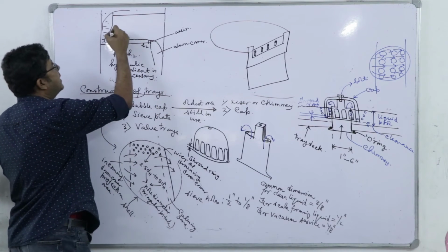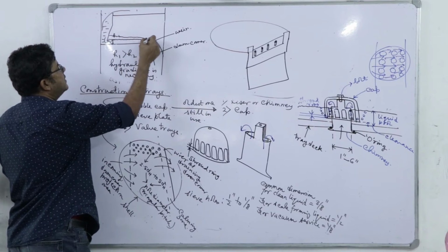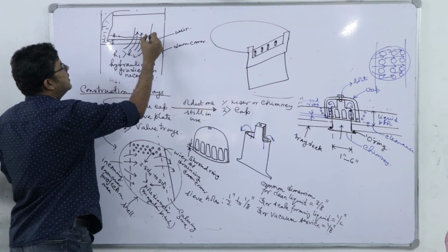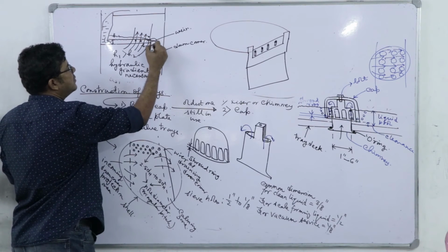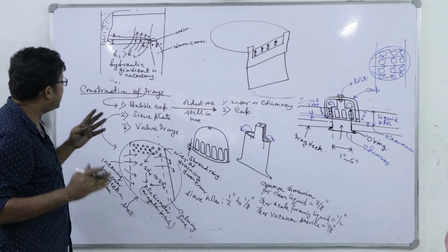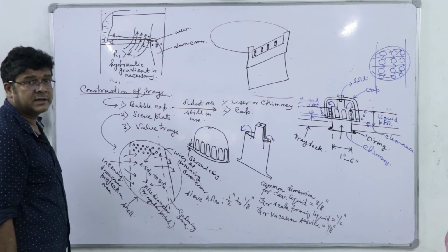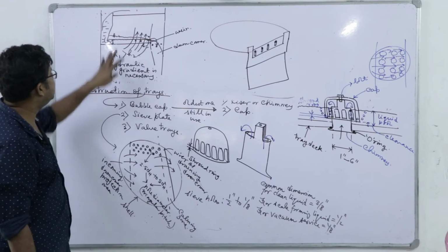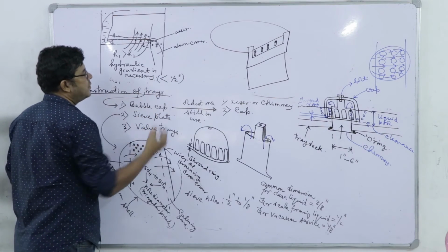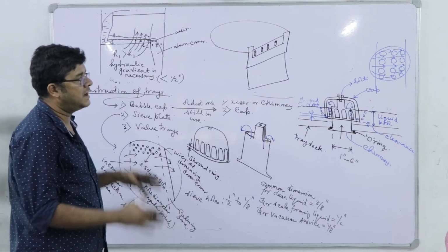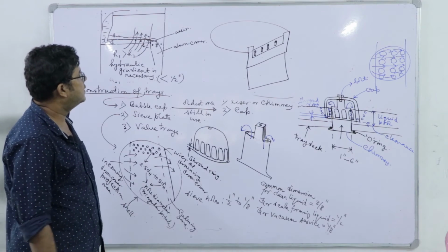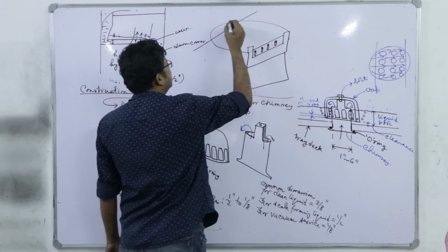However, if I have a very high hydraulic gradient, like liquid depth is high here and low here, the gas bubbles majorly pass through these regions, and eventually the gas bubbles will be entrained into the downcomer, and this part of the tray will remain ineffective. So, if the hydraulic gradient is not properly adjusted, it may cause severe non-ideality in this operation. Generally the hydraulic gradient should be kept less than half an inch, very low, and based on that we have a more or less uniform distribution of the gas bubbles throughout the entire passage of the liquid.